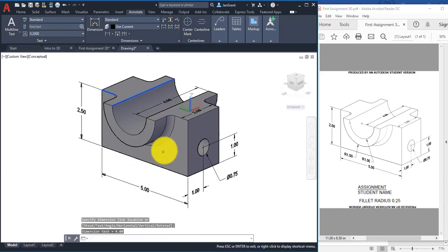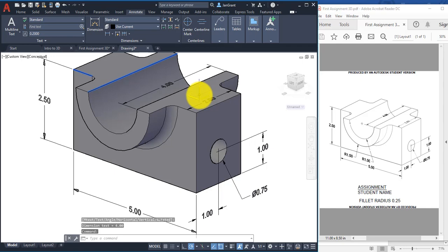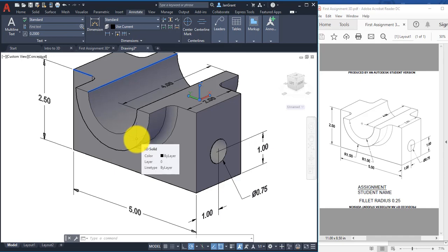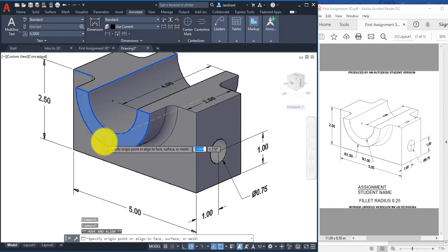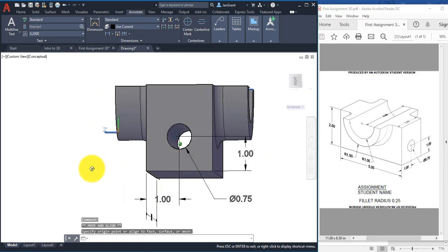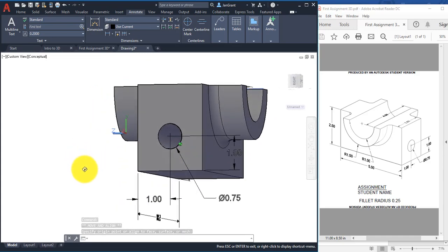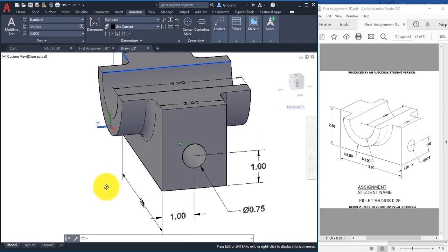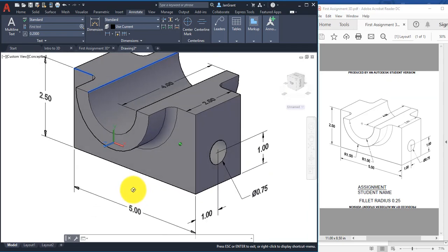All right, now the last surface is going to be the surface that's out here away from the box for the dimensions for the radius. I'm going to go ahead and pick the UCS icon up. This is a tricky one. You want to make sure that you're right on that curve. And sometimes I hold my shift key and my wheel of my mouse and I orbit around just to make sure that it's really on that surface. Sometimes it goes back to one of those object snaps and gets off that surface.